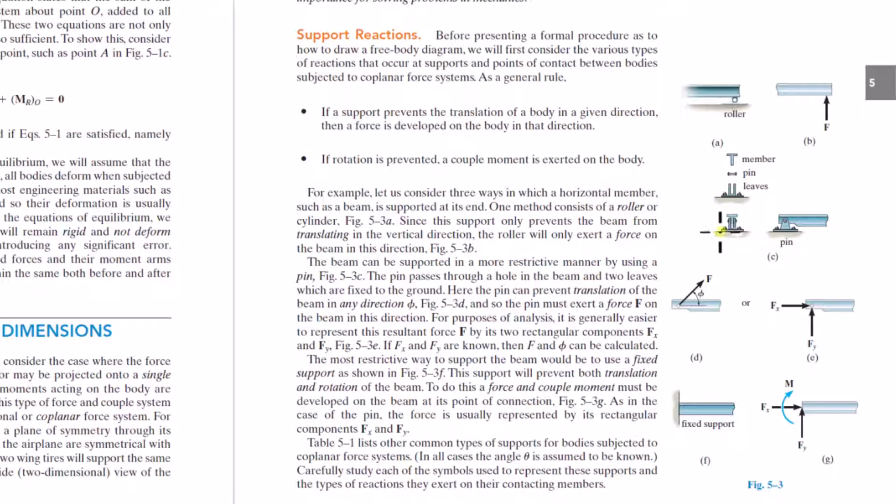But the idea is, when you think about the magnitude of the loads that the pin is resisting in the actual directions, if there was any kind of rotating motion in this direction that was even in the ballpark of these forces, it would break that connection. That pin connection is not designed to stop any significant rotations or even translations in this direction, right? You might say, well, it can prevent translation. This kind of connection is not designed for that. The whole thing would fail.